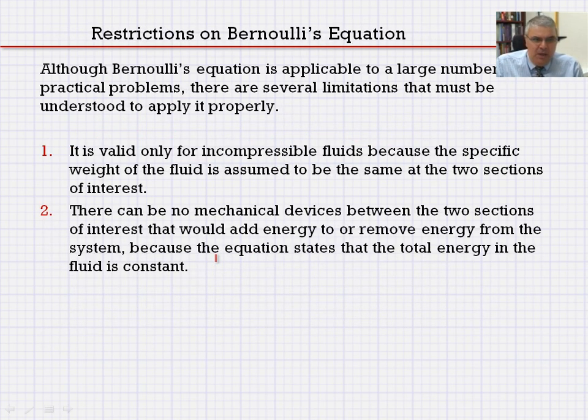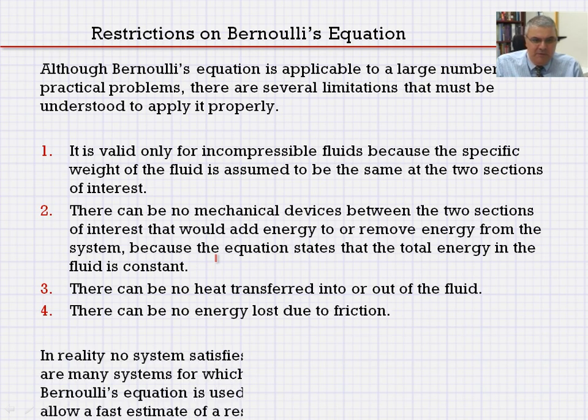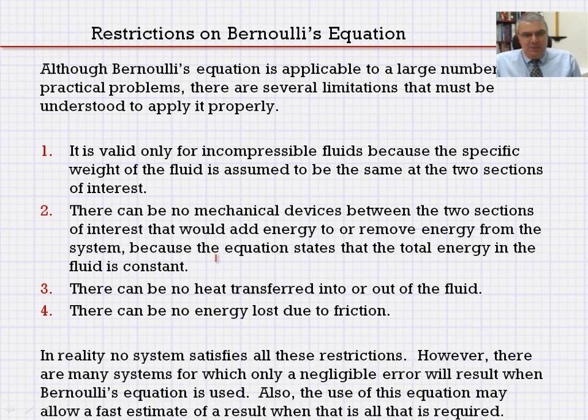Some of the restrictions of the Bernoulli equation are of special attention. It is important to realize that Bernoulli equation is only valid for incompressible fluids, because the specific weight of the fluid is assumed to be the same at the 2 sections of interest. If the specific weight of the fluid changes, then we cannot apply Bernoulli equation for those 2 points. So please keep in mind the principles that we derived the Bernoulli equation based on.